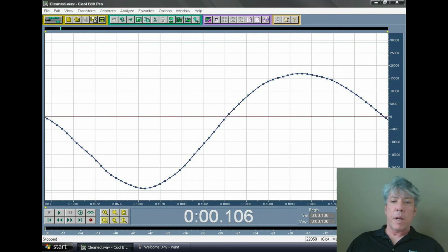But that's the resolution, or how much the temperature would have to change in order to detect that the temperature has changed. Now obviously you're not trying to measure the temperature from absolute zero to an infinite temperature. You've got to decide on a range, but in that range the resolution would end up being pretty good. And as a matter of fact, most PLCs' analog inputs and outputs are either 10 or 12-bit. They're not 16-bit. So with 10-bit you get 1,024 different steps. Every time you add a bit it doubles the resolution, so with 12 bits you get 4,096 different steps. And again, that's quite often adequate for most processes.